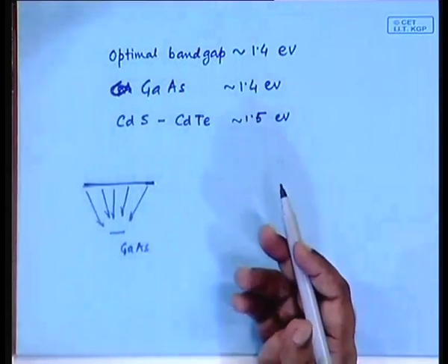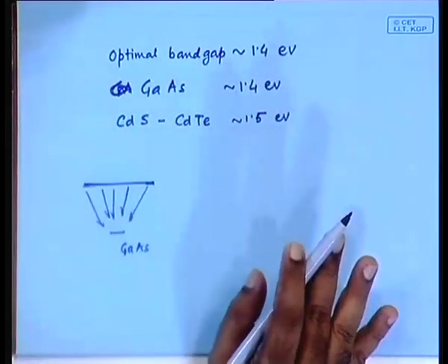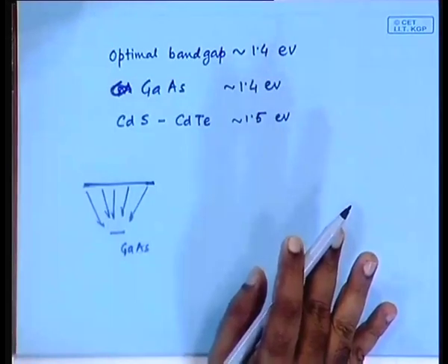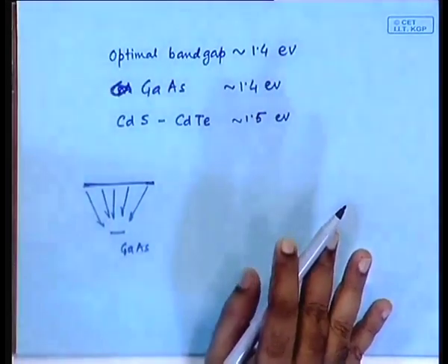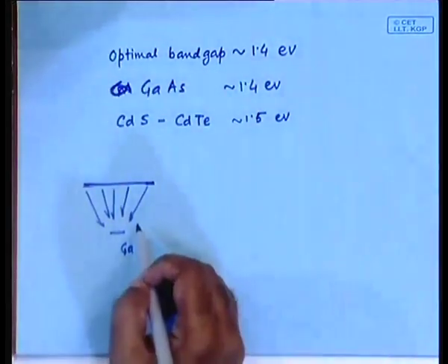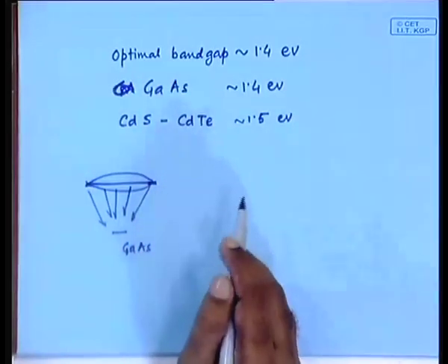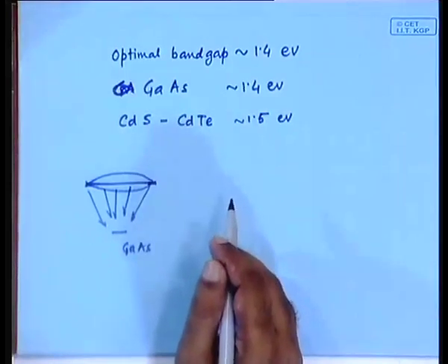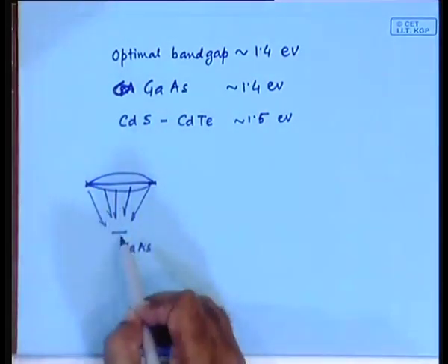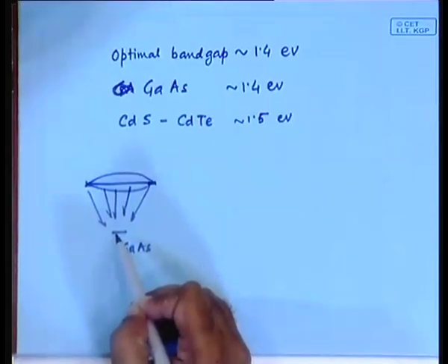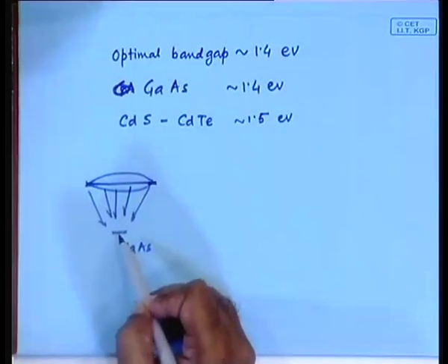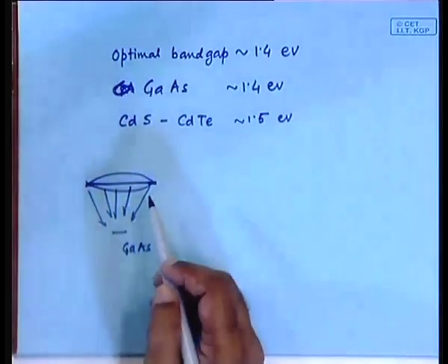What kind of concentrator can it be? Have you already learned concentrators? Yes, right. So, you have learnt that there are a few types of concentrators. One is the reflecting concentrator, the other is the refracting concentrator, and out of the refracting concentrators, you have learnt that a whole big lens is of no use. We normally use Fresnel lenses. Okay. Yes, the Fresnel lenses are also considered in conjunction with gallium arsenide solar cells. So, very rarely will you find gallium arsenide solar cells considered as just a standalone system; they are used in conjunction with some kind of concentrator.